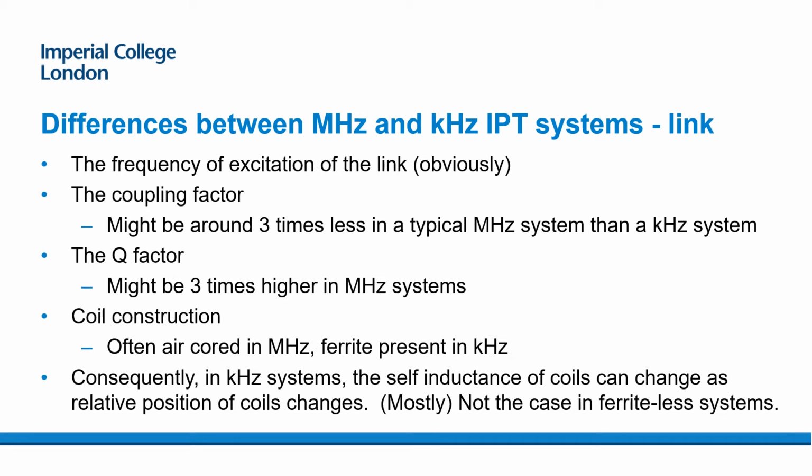The downside is that the coupling factor will be lower, typically, than a low frequency system. We don't have all the ferrite in here, where we are creating magnetic field over a larger area typically than the lower frequency systems. But there's perhaps some advantage to that in some regards, because it typically means that I can go over a longer distance than I can with a lower frequency system.